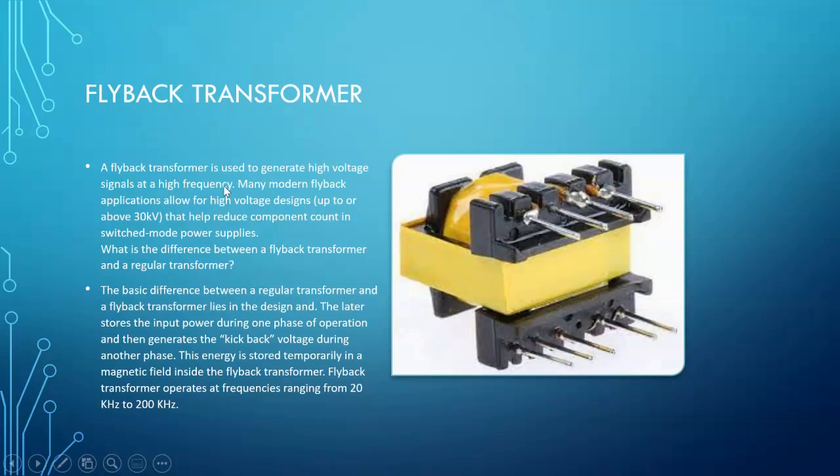A flyback transformer is used to generate high voltage signals at a high frequency. Many modern applications allow for high voltage designs up to 30 kilovolts that help reduce the component count in switching mode power supplies. The basic difference between a regular transformer and a flyback transformer lies in its design.